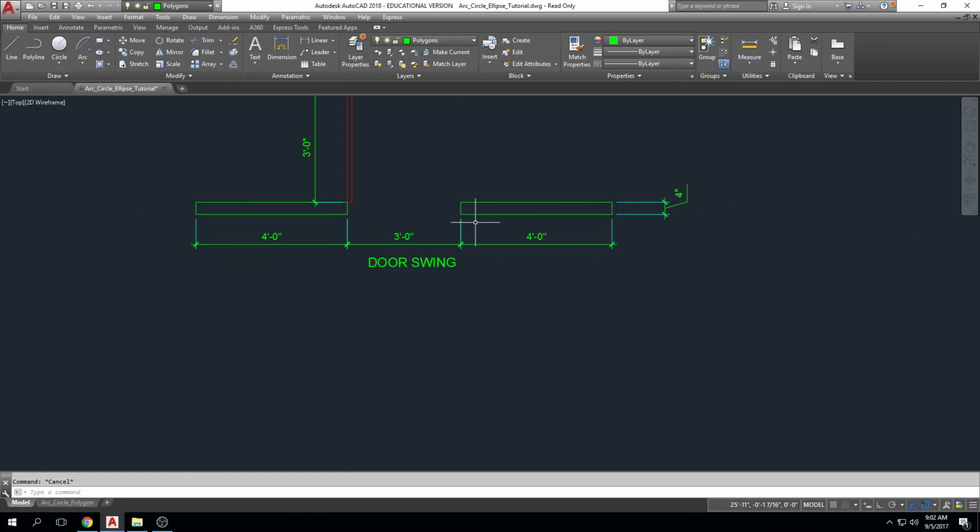So I'm going to use line to create this object. I come up, click on line, right? I can line this up using object tracking if I want. Click. Ooh, I need to move in the direction I want to go, but this needs to be straight, so I turn my ortho on. F8. Right? Now I have my straight line. I type 4 foot. I could have also typed 48 inches. Okay?